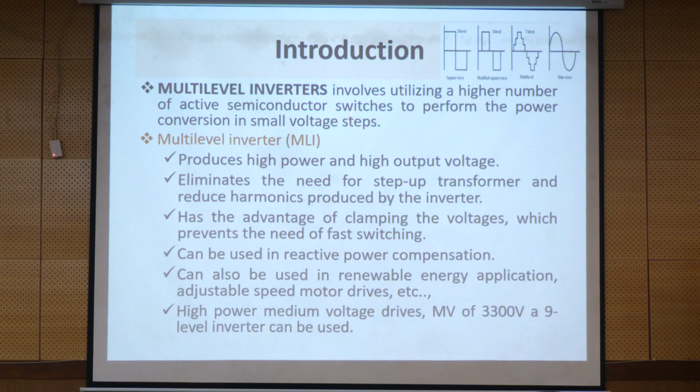This multi-level inverter involves utilizing a higher number of active power semiconductor switches to perform the power conversion in small voltage steps. This is what we finally get. Our objective is to get the original waveform close to the sinusoidal waveform, which can be achieved in smaller voltage steps.